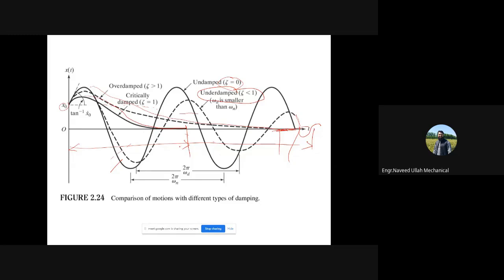ठीक है, इसकी simple example you can take that at the back of the door. ठीक है, आपने डैम्पर देखे होंगे, कन्वेंशनल डैम्पर. तो एक जो अनडैम्प्ड सिस्टम है, अगर डैम्पर है ही नहीं, सिर्फ स्प्रिंग है, तो ideally if you open that door, it should oscillate forever and the amplitude of vibration will not decrease. ठीक है. Similarly, if there is damping pressure over there but it is not sufficient, तो 4-5 oscillation के बाद जो है ना ये अपने ओरिजिनल पोजीशन के ऊपर आ जाएगा.